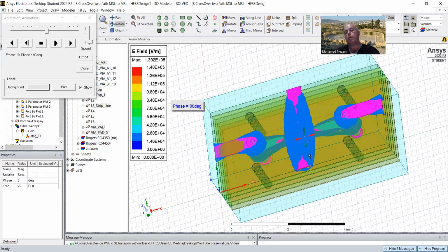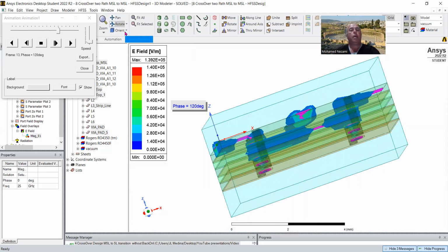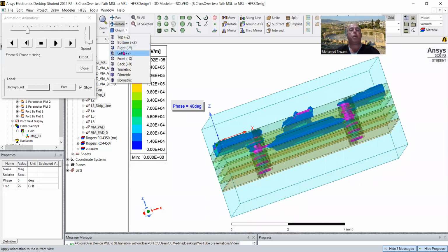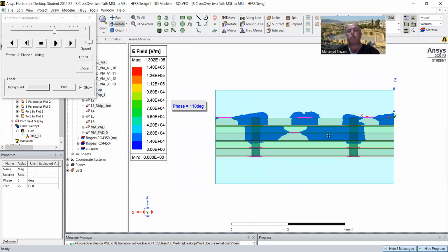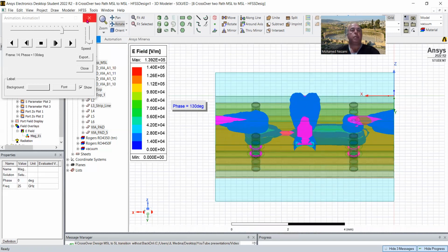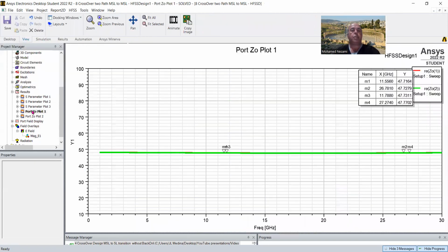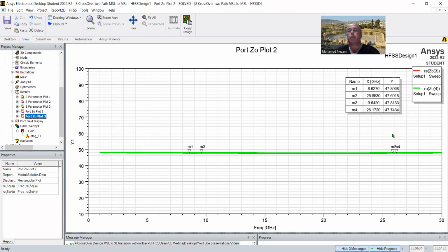as you can see, there's a ground plane and there's another ground plane below, because the other one is a stripline sandwiched between 2 grounds. As you can see, this is ground, this is ground. Okay. And of course, if we check the impedances, we still got 48 ohms in here, and the other impedance is 48 ohms. So this is successful.